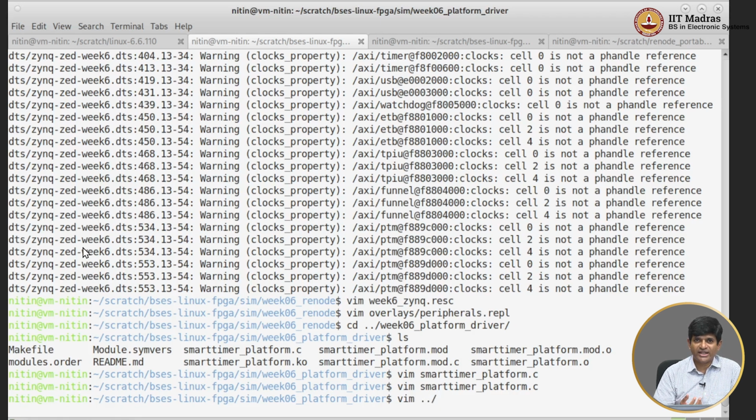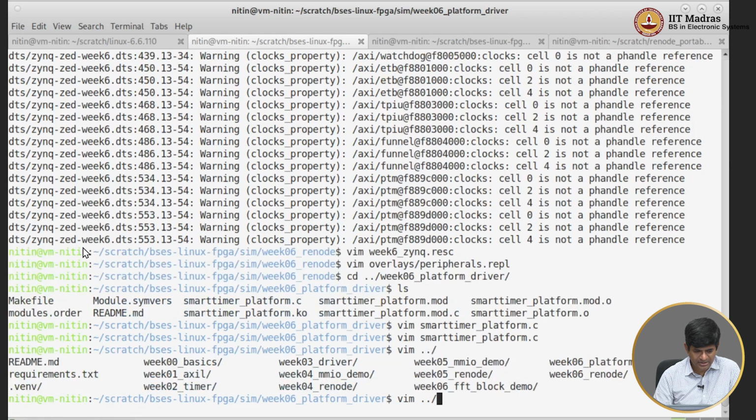There are other ways such as using user space events and so on, by which module drivers can be loaded at runtime as required, but for now I'm going to use a brute force approach where I just say look at everything that was specified in the device tree, try to load a module for it, right.